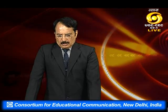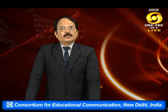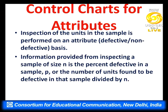Two versions of the control charts will be examined. First one is control charts for attributes, and the second is control charts for variables. We have already discussed attributes and variables. Control charts for attributes: inspection of the units in the sample is performed on an attribute, as already discussed, defective or non-defective. That is the only information we get from the inspection.